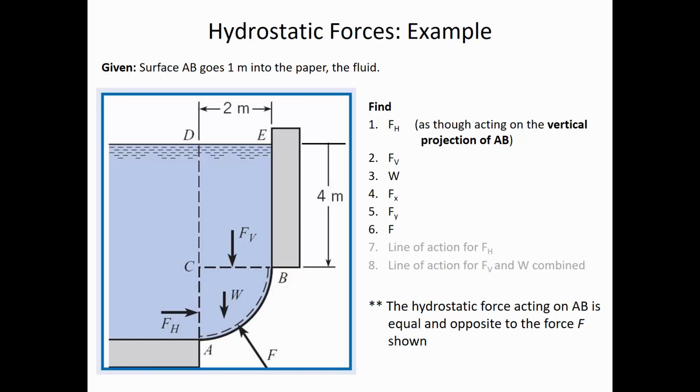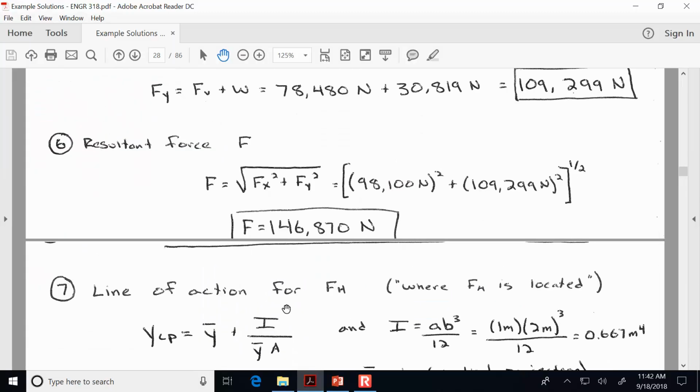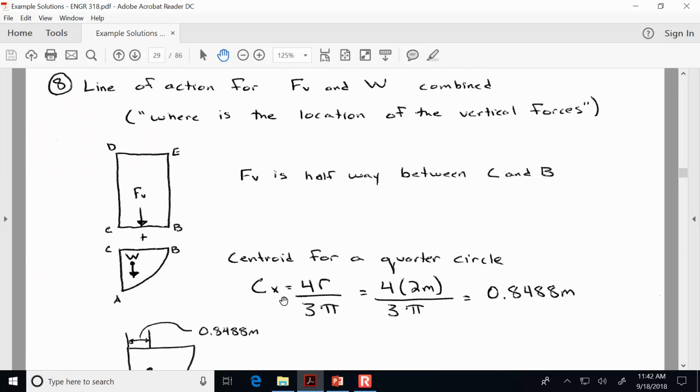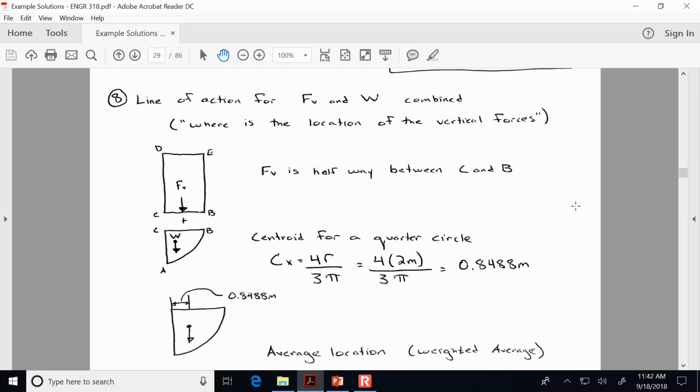And if we just substitute in the known values for that, it's 0.8488. So what that's talking about is how far from the left edge to where the center of area is. And we would expect that it's going to be less than 1, because remember, it was 1 to get to the middle from the two sides.